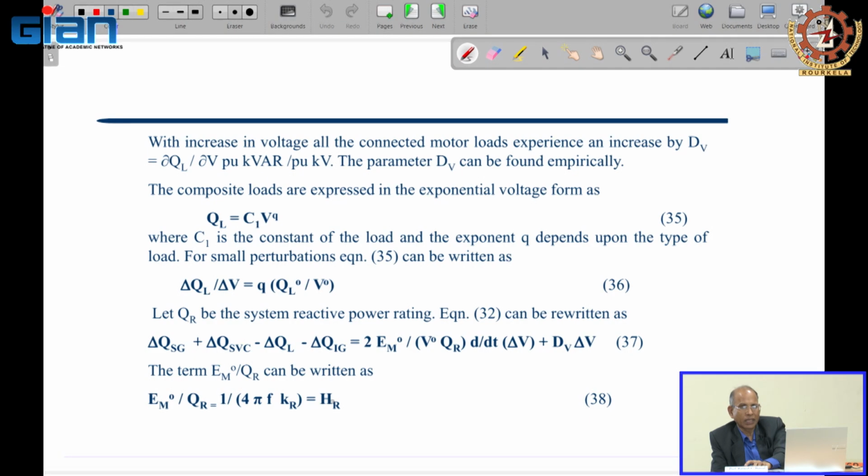So, basically, as you are doing the power equations, as we mentioned, load frequency control. Okay. As you had in the power system, you have got the turbine, then generator in the feed forward loop, then the feedback loop, you are taking the signal from the output side, that signal you are feeding to the input side.